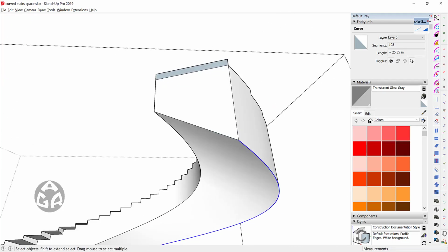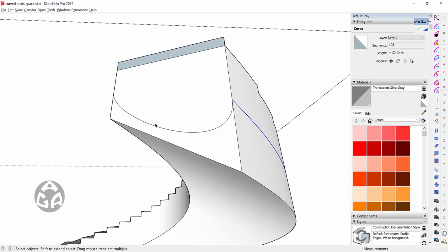And I will use again this Classic Bezier curve, and then click once in the midpoint of this line, and then in the midpoint of this line, I will click once over here and then double click to confirm this curve. So I will type 60s to have like 60 segments for this curve, and I will click this curve and then copy it over here, and then another one over here.